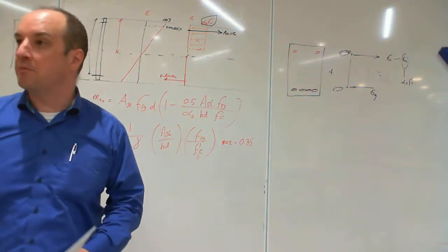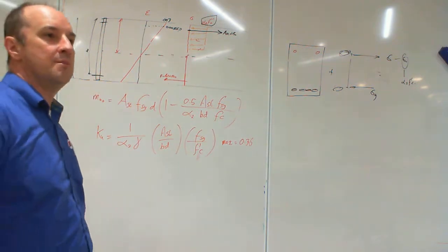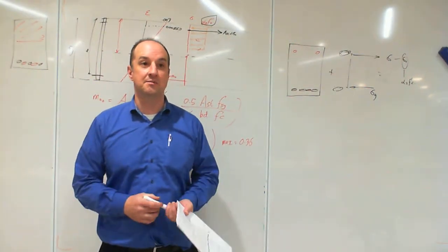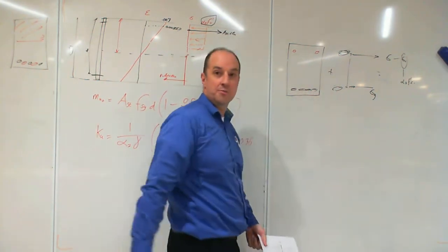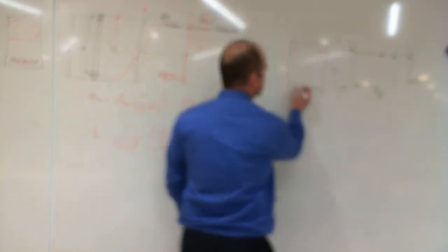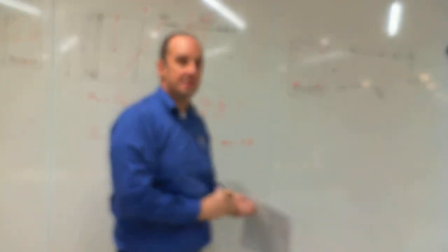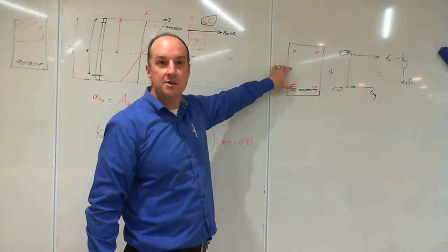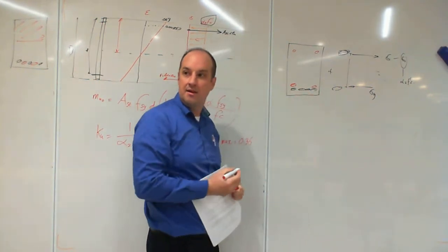All right, there's one more complication I've got to put in. Often when we're talking about doubly reinforced concrete beams, we're talking about beams which have a lot of steel in them. And so there comes a point where you can't get all the steel in one bottom row. So you need to throw the steel in two rows. And that, as you appreciate, changes the lever arm. So you need to take the centroid of all that steel as the lever arm.